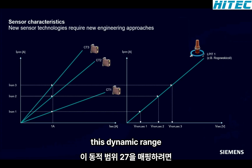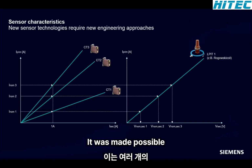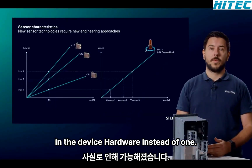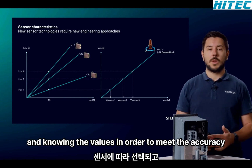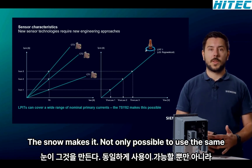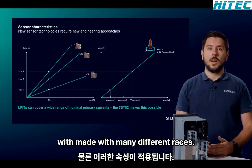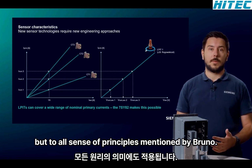In order to map this dynamic range, the 7SY82 must be able to work with a range of secondary nominal values. This is made possible by the fact that several measuring ranges are now realized in the device hardware instead of one. And these are selected depending on the sensor and nominal values in order to meet the accuracy requirements. This now makes it not only possible to use the same Rogowski coil for different nominal currents, but also sensors from other manufacturers with maybe different ratios. Of course, these properties apply not only to Rogowski coils, but to all sensor principles mentioned by Bruno.